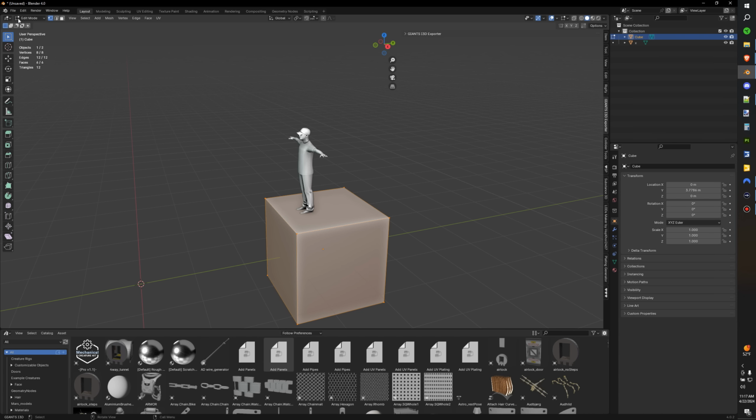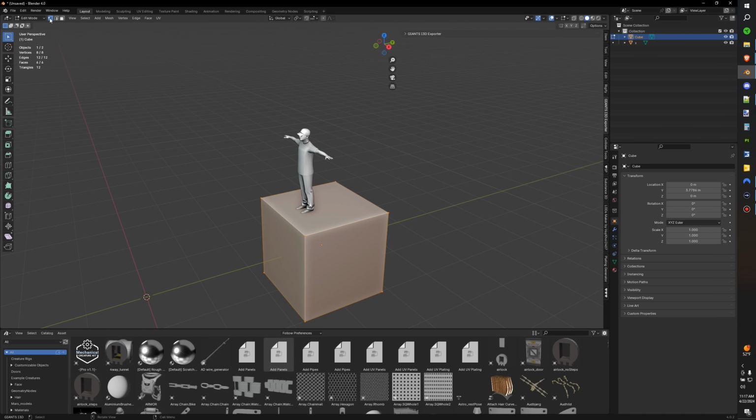Edit mode, I mean up here, you can look at this tab up at the left hand. You have object, edit, sculpt, vertex. We're not going to get into most of this. We're going to stay in object mode and edit mode for right now. But in edit mode, we are going to come right up here to these three dots. You have vertices, edges, and faces. We want to snap his feet to a face. So we're going to select the face button. You can alternatively press 1, 2, or 3, and that'll cycle through them.